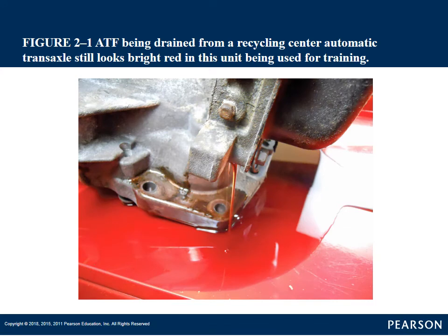Here's a picture of transmission fluid coming out of a transmission. This is a nice red transmission fluid. That's kind of what we want. When it starts getting brownish in color or black and burnt, that's when we need to see about repairs or replacement. And when we get into transmission service and diagnostics, we'll talk more in depth on how to diagnose transmission issues or a need for service by looking at the fluid of the transmission.